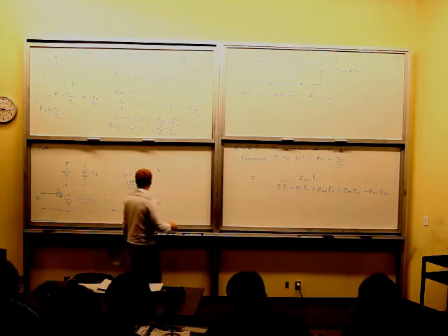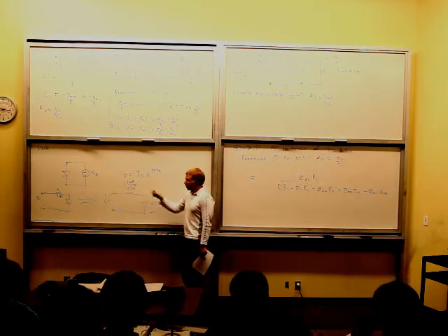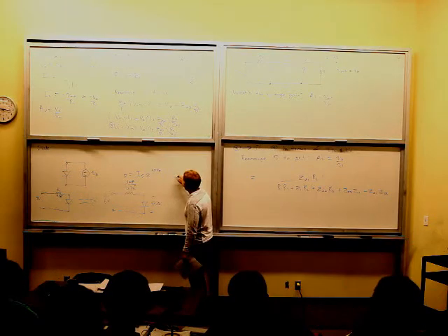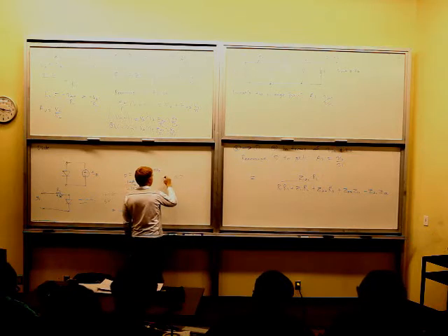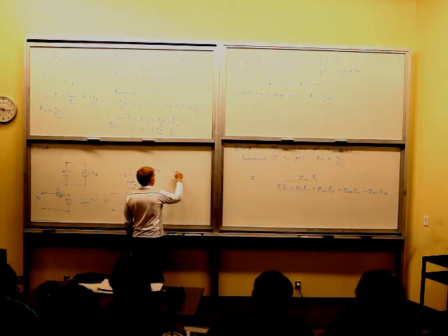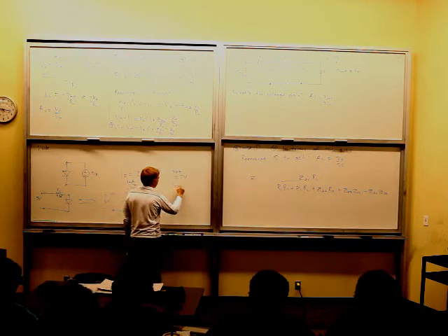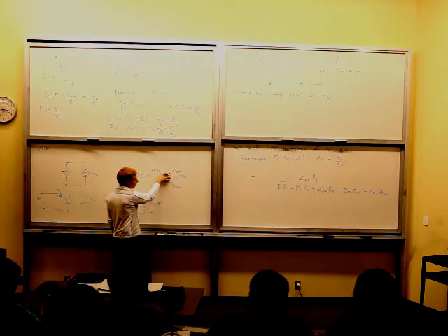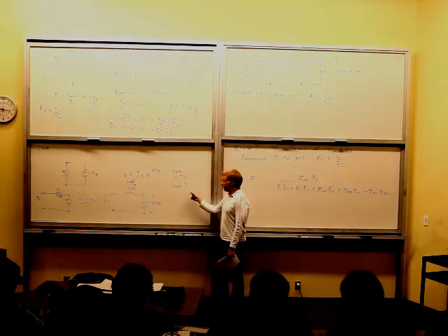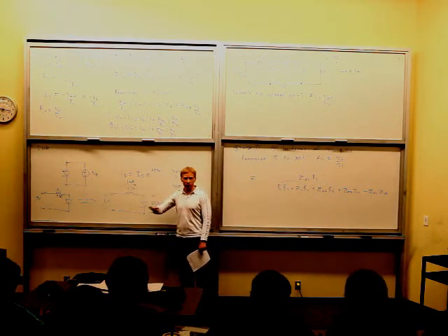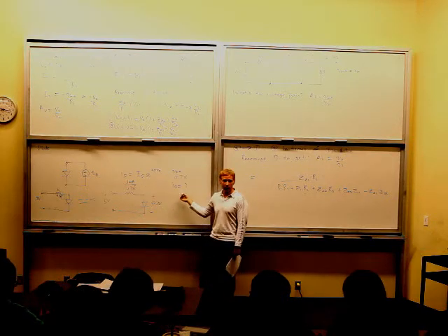Now, here's what I would do. I would say, okay, I'm assuming this is 0.7 volts. I got 1 milliamp coming through. Is my manufacturer specified value approximately 0.7 volts? They'll specify a value, right? They'll say the diode was tested at VD equals 0.7 volts, and at ID equals something. So given an exact voltage of 0.7 volts, we got a diode current of something, and they're going to tell you what that is. If that's approximately 1 milliamp, good enough. If that's what you came up with, and it's approximately equal to that, great.